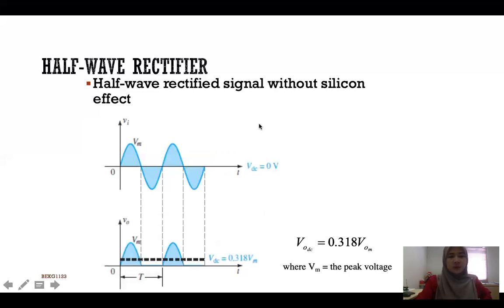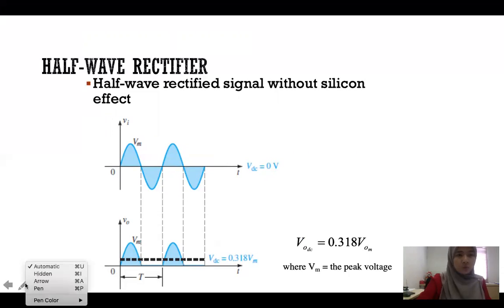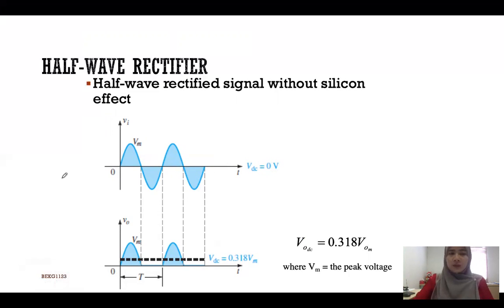So the figure over here shows you what happens in the half-wave rectifier. This is the V in, this is the V out. This is the input, this is the output. The input is an AC sine wave, but the output will become something like this. Because this is forward bias. During reverse bias, V naught is equal to 0. And this is the second cycle, and so on.